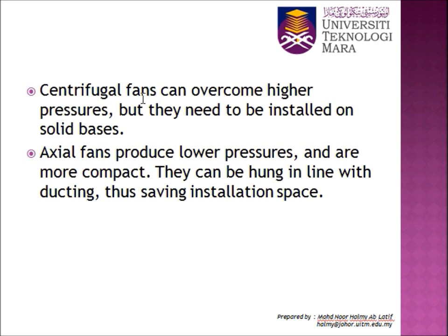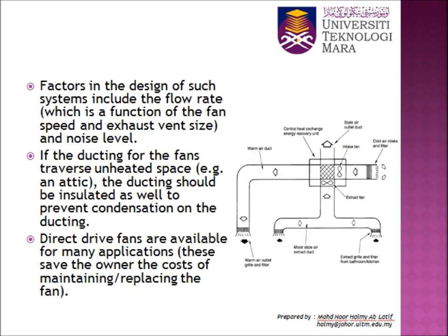Okay, centrifugal fans can overcome higher pressure, but they need to be installed on solid basis. Axial fans produce lower pressure and are more compact. They can be hung in line with ducting, thus saving installation space.